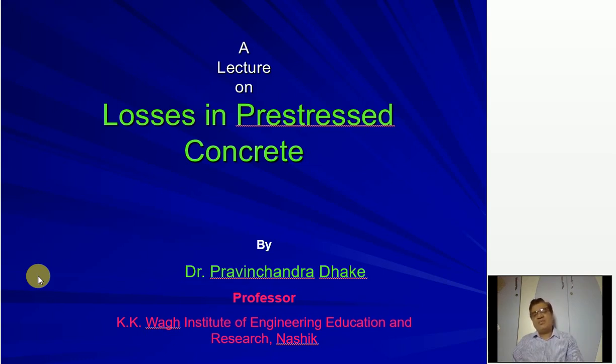Desired degree means what? While designing the concrete section, we have to decide how much stress can be counterbalanced. That depends on the pre-stressing force and the cable profile and its eccentricity. While designing, estimation of losses in pre-stressed concrete is very important because total loss of pre-stress is 12 to 18%. It's a quite considerable amount, and hence detailed estimation is always required. So we'll see today what exactly loss of prestress is, which are the different types, and how to calculate this loss of prestress.